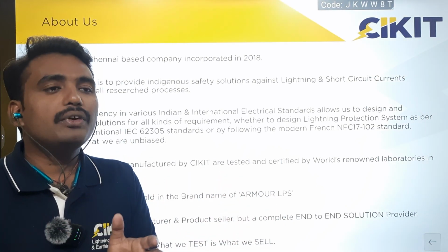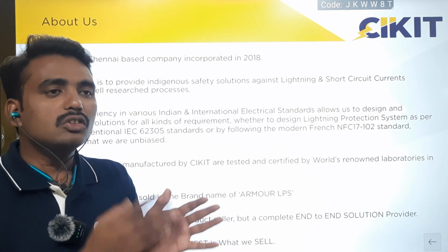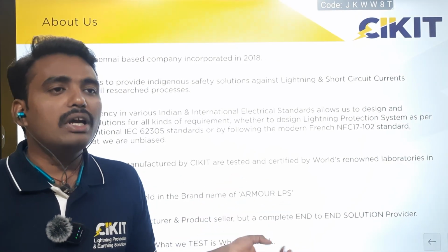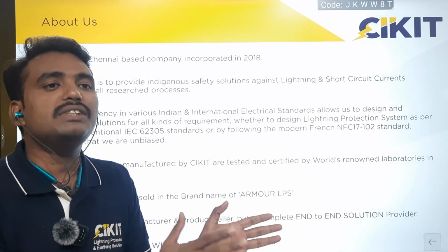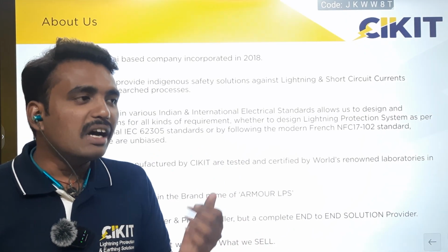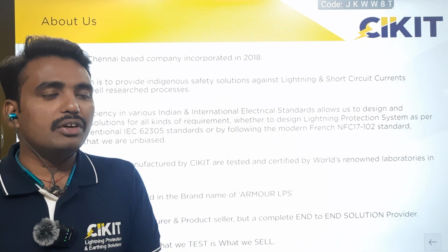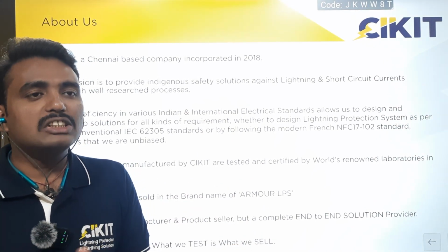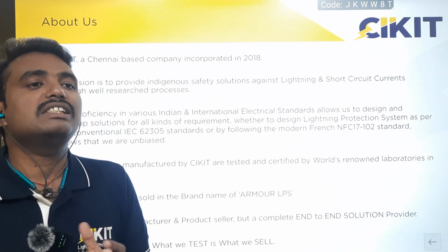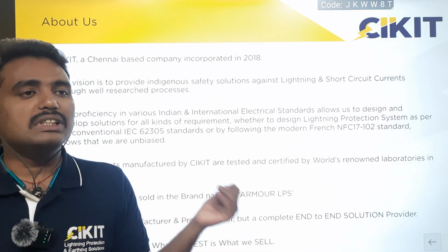For example, if you take oil and natural gas industries, we cannot go for the same 62305 standard. We have to go for a separate standard called OISD-GDN, which was published by the Oil Industry Safety Directorate, which is very specific to the oil industry. So we provide customized solutions based on site conditions, and end-to-end solutions starting from site survey, risk assessment calculations, design, material supply, installation, and periodical maintenance, which includes auditing of the existing lightning protection system as well. We provide end-to-end solutions for both lightning protection and earthing.